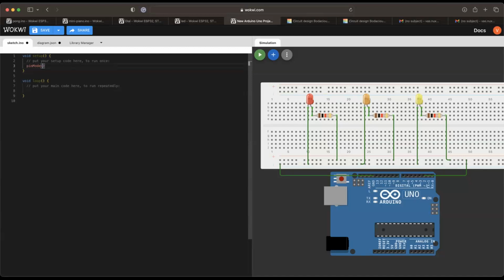So we connected it to pin 2. Well, I did. And then we say 2, and then we say it's the output, because that's the output we want it to be. So the output digital PWM is pin 2, and we want that to be the output, not the input or input below. So output just selected. Since we're taking information in, the output should be that the LED turns on. So that's why pin 2 is the output. And then that's it for the setup.